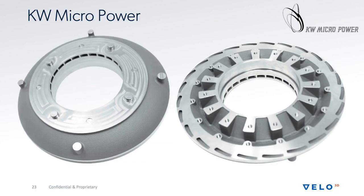To use this in a real example, I'm showing a part from a company called KW Micropower. This is a turbine diffuser. It's about 10 inches in diameter. It's a titanium part, and they were bidding this part out to a number of manufacturers and getting no bids from almost everybody. The reason being mostly, kind of a sidebar, it's very difficult to print large titanium parts without cracking because of the brittleness of the printed titanium. And VELO has a proprietary process to mitigate some of that, to print large parts like this.